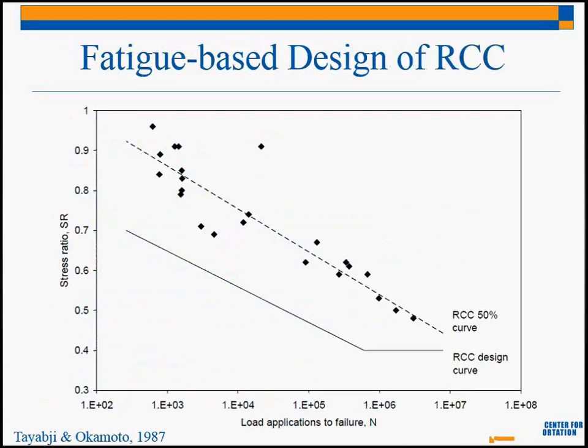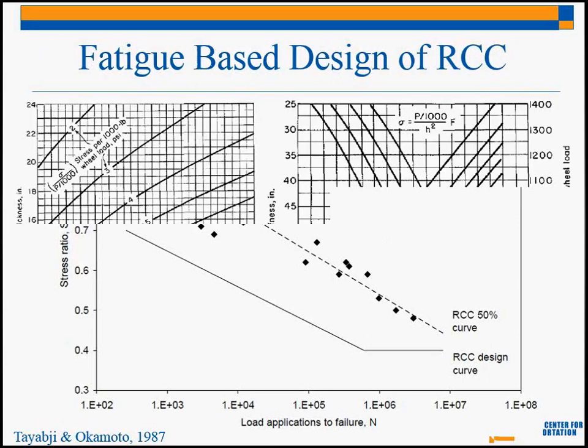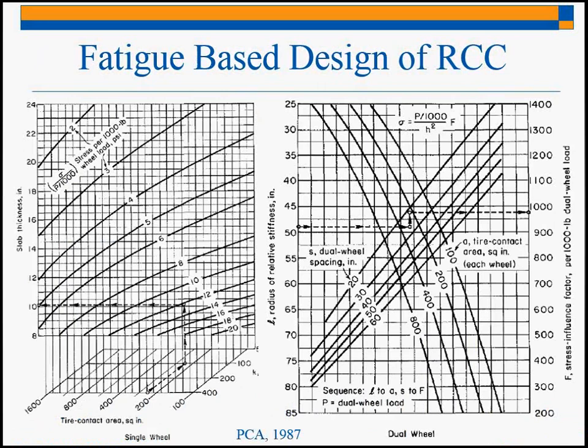So going back to the design of RCC pavements, this is based on work by Tayaji and Okamoto in 1987 when they were with CTL. It is a fatigue-based design, and it's mainly based on the flexural strength of our concrete. There are some issues with that, which I will talk about as we go. But that's basically how it was designed for a while.